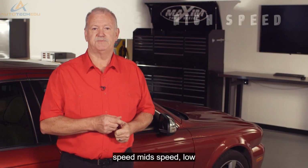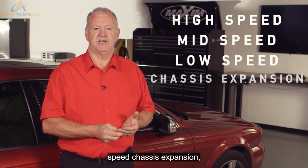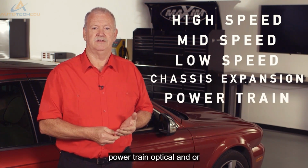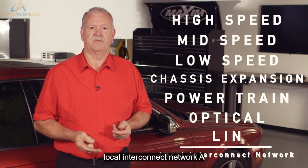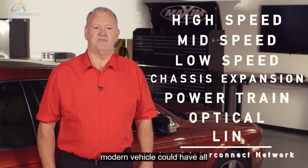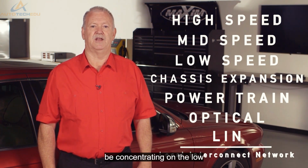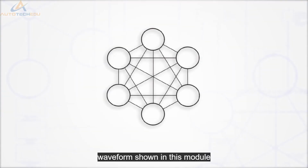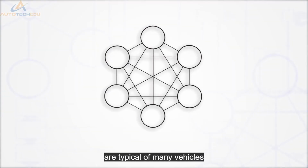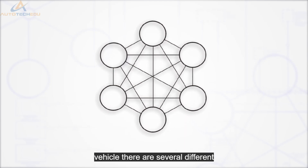We can have high speed, mid speed, low speed, chassis expansion, powertrain, optical, and LIN, or local interconnect network. A modern vehicle could have all of these systems or just a few. We'll be concentrating on the low speed bus for this module. The circuit and waveforms shown in this module are typical of many vehicles. Always remember to check the appropriate data for your vehicle.